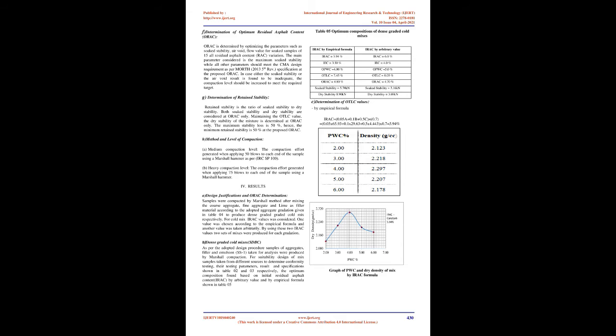C. Coating test and determination of optimum pre-wetting water content, OPWC. Using the IEC value, the coating test is carried out by mixing dry aggregates and filler with varied amounts of water. After the pre-wetting of aggregates, the asphalt emulsion is added and then mixed for about 2 to 3 minutes until uniform coating is obtained. The optimum pre-wetting water content, OPWC, is the one that gives the best asphalt coating on the mineral aggregates, in which the mixture was neither too sloppy nor too stiff. The degree of coating should not be less than 50% by visual observation.